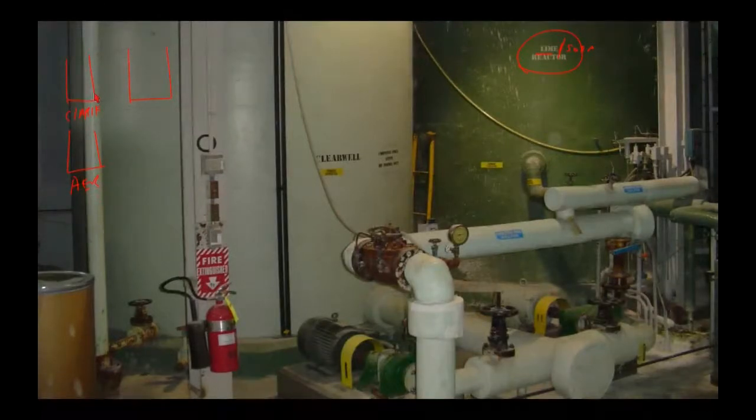Then what we're going to do is take the water from each one of those with a pump, so we've got to repressurize it, and we're going to pump that water into our lime reactor with a bunch of chemicals that go in there, and that will go to the bottom forming sludge, and the relatively clean water, now quite a bit softer, will overflow into another tank that we call the clear well.